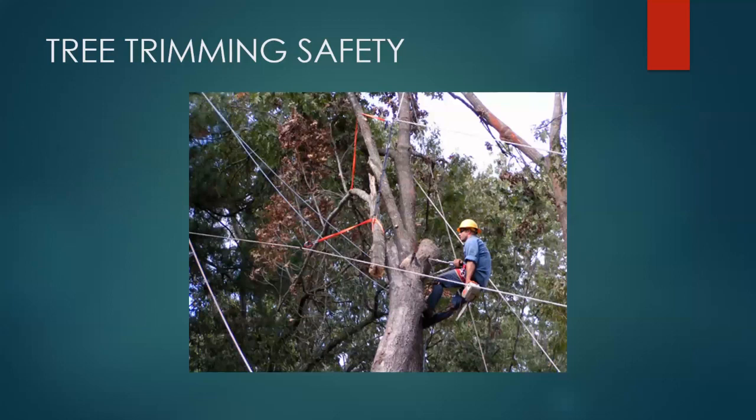Only qualified line clearance tree trimmers are allowed within 10 feet of energized power lines. Qualified employees are those who are knowledgeable in the construction and operation of electric power generation, transmission, or distribution equipment involved, along with the associated hazards. To become a qualified line clearance tree trimmer, you will need additional training that is beyond the scope of this webinar.